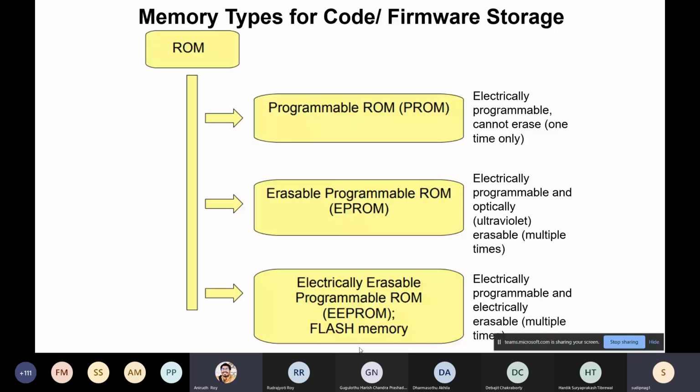In more modern microcontrollers, you don't have EEPROM, you have only flash. But for Atmega, which is a slightly older variant of the RISC microcontrollers, 8-bit, you can store the user data in EEPROM. As I said, suppose in your remote control, you are using the microcontroller for controlling a robot remote control, or a drone remote control, for example.